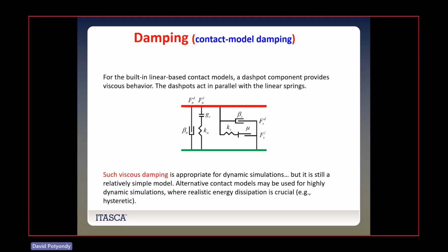And this is the type of thing that this damping is going to keep at a negligible level, so that you don't start getting that whole thing shaking like crazy. So therefore, you can do this. If you load that thing slow enough, it basically is going to behave in a quasi-static fashion. Okay.